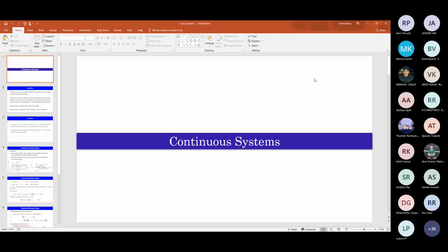The orthogonality is valid here, because whether the system is continuous or discrete is our modeling approach, but the system behavior is not going to change. If you discretize a continuous system to a multi degree of freedom system, our response should match the exact continuous system model.